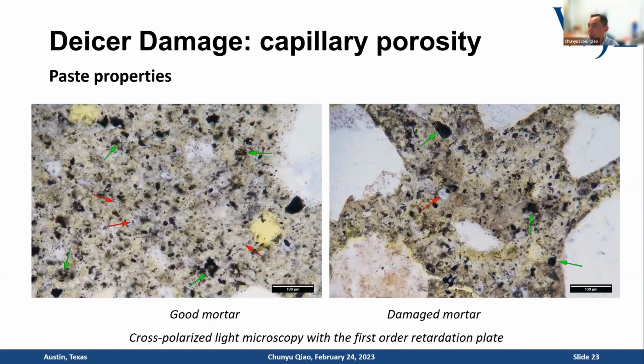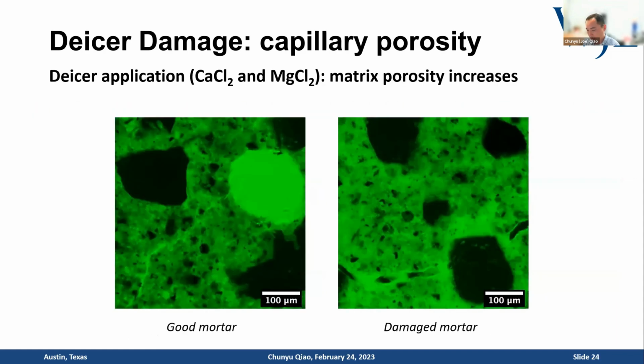So that's an indication of calcium leaching, using just standard petrographic microscopes. And we also want to look at, okay, your concrete is losing calcium, just like human bones lose calcium. That's not a good thing. So how can we tell how much more porous your concrete is?